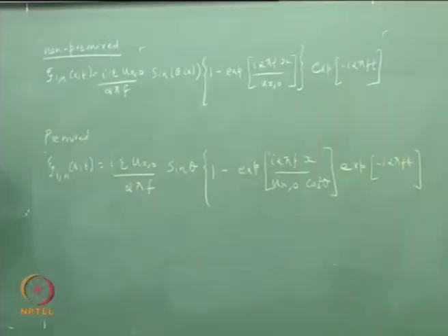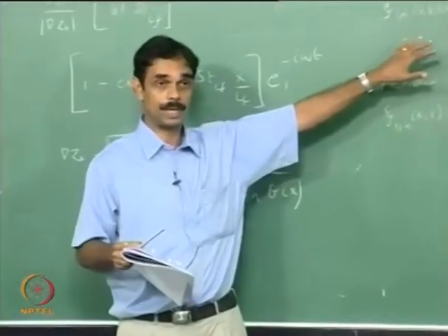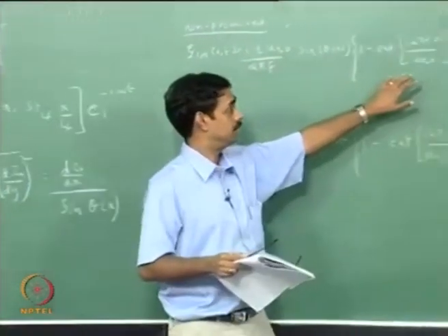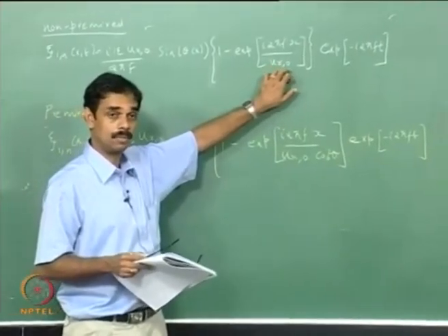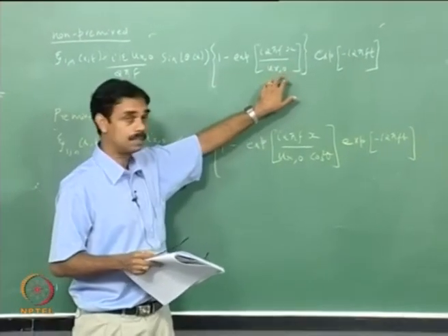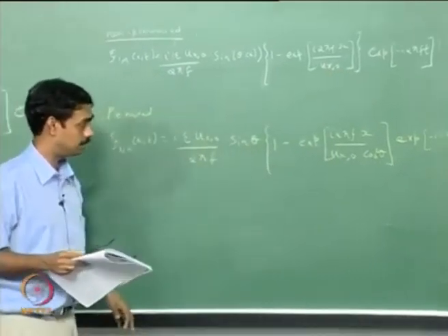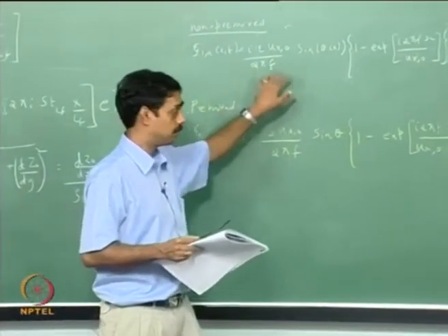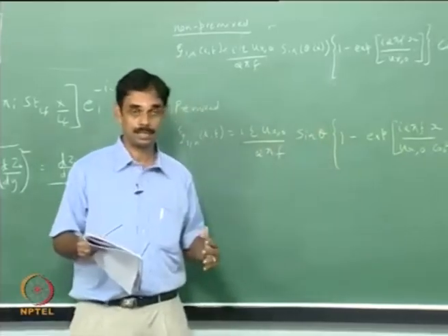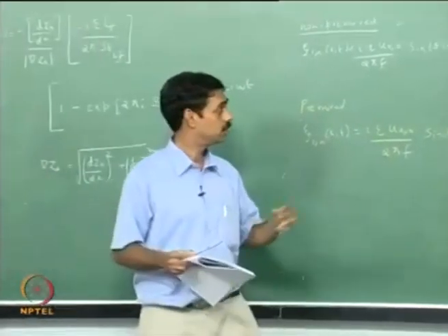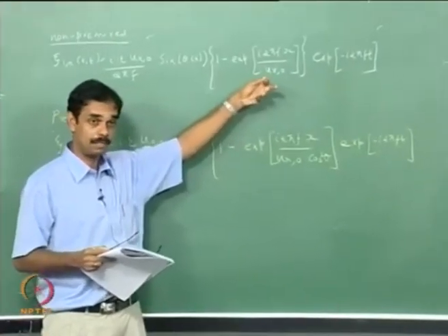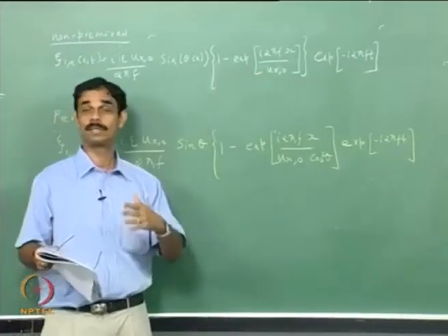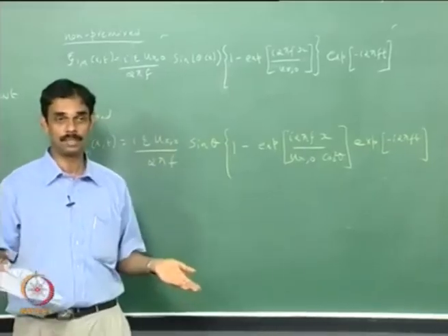So the diffusion flame or non-premixed flame does not propagate. So you have the speed as the convection speed itself. So wrinkles will be propagating only with this convection speed, whereas that is for the non-premixed flame. For the premixed flame, the flame is trying to propagate and then the flow is trying to come in. So you will not get exactly ux0, but something that depends on ux0 and the flame angle, because the flame angle will be reflecting the flame speed.